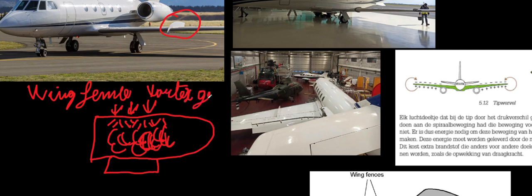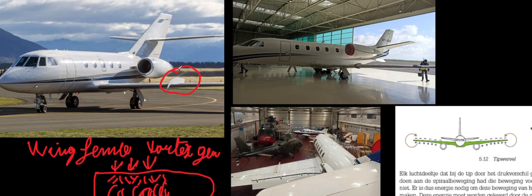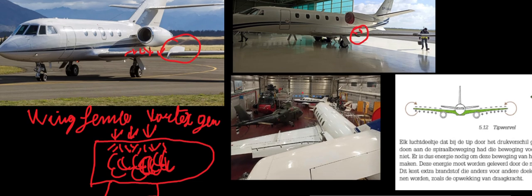Now, we're going to look at a wingtip fence. It's definitely not a vortex generator. If you look at what vortex generators are, they would be these little plates on the side of the aircraft, definitely not one big plate, or like we see here, also very different from a vortex generator.